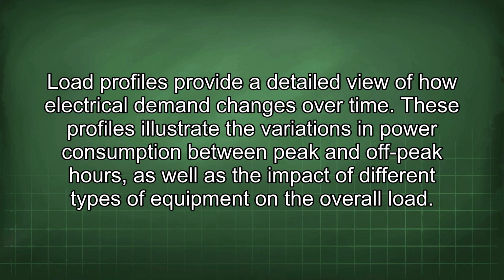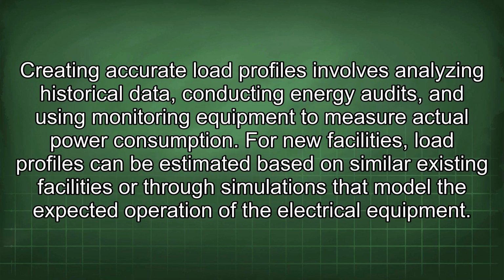These profiles illustrate the variations in power consumption between peak and off-peak hours, as well as the impact of different types of equipment on the overall load. Creating accurate load profiles involves analyzing historical data, conducting energy audits, and using monitoring equipment to measure actual power consumption. For new facilities, load profiles can be estimated based on similar existing facilities or through simulations that model the expected operation of the electrical equipment.